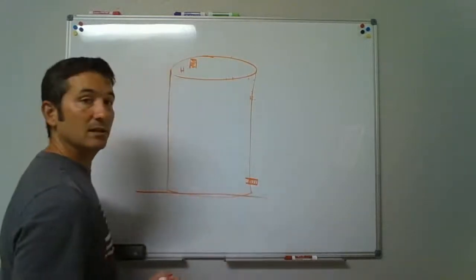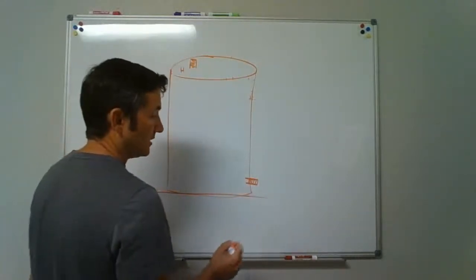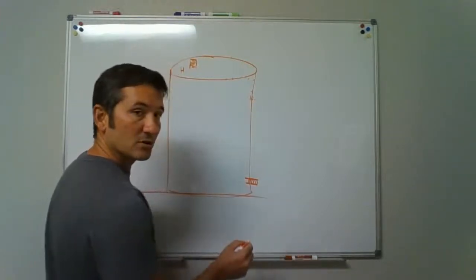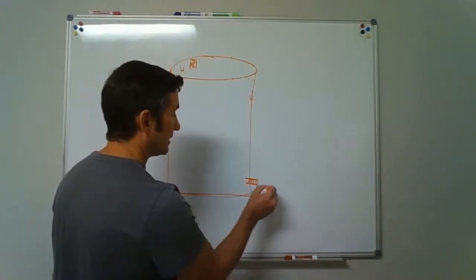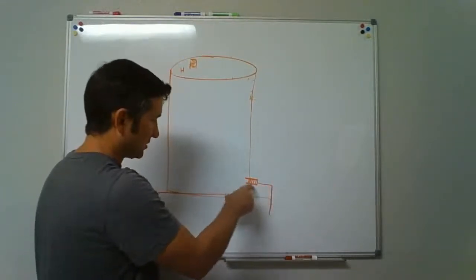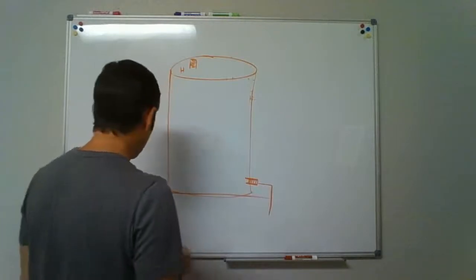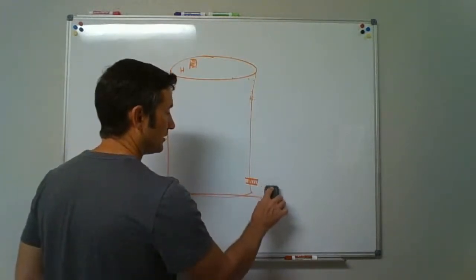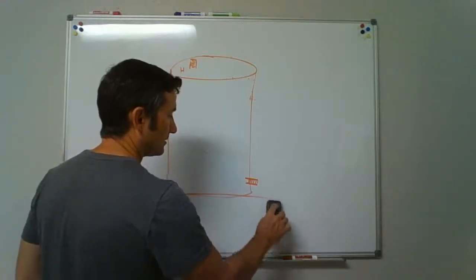Now, what's easy is if this is up in the house, a lot of them that I've seen installed, the water line, since they're underneath in the crawl space or whatever, they just pop the water line up and go right into the side. See, because that's the path of just so quick and easy right there. Okay, but this code says no, we cannot do that. You have to install a vacuum breaker.